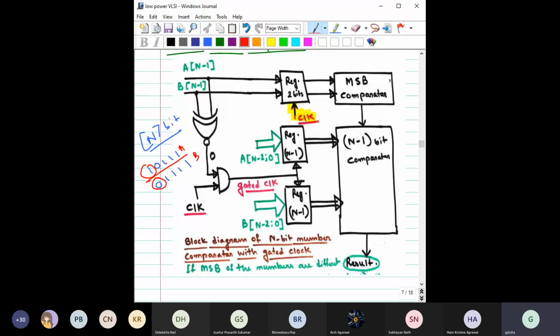See, when you are not comparing the remaining bits, how do you compare? You have to do some operation. Which gate will help you in comparison? XOR. So the output has to change, right? So the XOR output has to be changed. So is it really required to check this many bits, if you can check only the first bit and tell that this number A is higher, right?